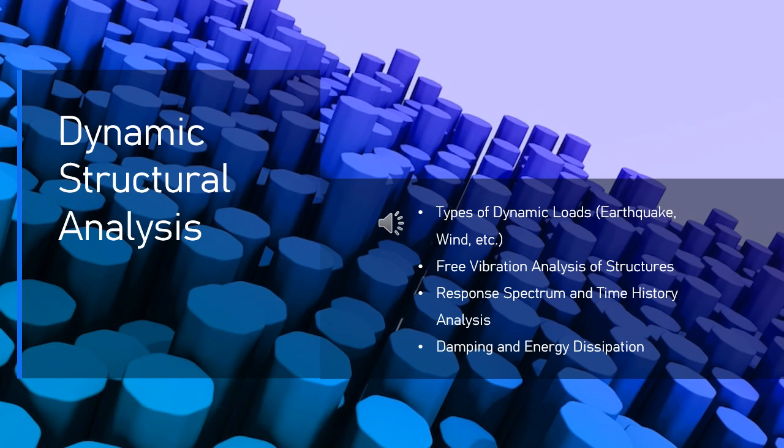9.1. Response spectrum analysis. Response spectrum analysis, RSA, is a method used to determine the peak response, such as displacement, velocity, or acceleration, of a structure subjected to a dynamic load, without solving the equations of motion for every time step. What is a response spectrum?